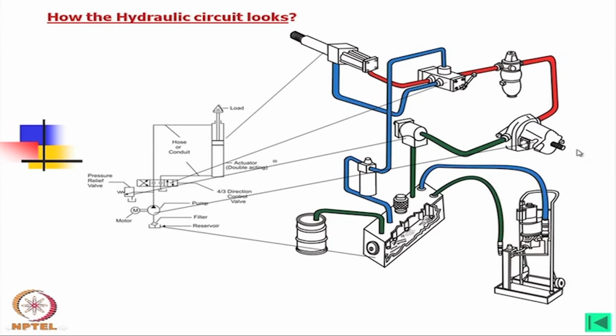However, this motor is not shown, whereas the reservoir is slightly elaborated and there is also another system shown which is to put oil inside. This we can do from time to time, it may be after 6 months, it may be after 3 months depending on the use, we can pump out the oil and filter it and again put it inside to reduce the contamination.